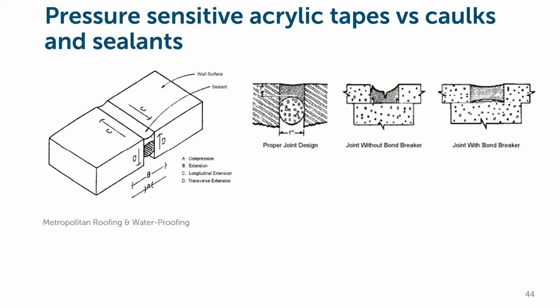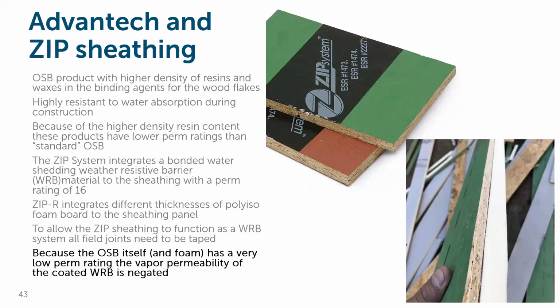But something I see all the time is that people tape their joints and everything, but they're not taping the rough opening sheathing back to the studs at the ROs, and they're not taping the Zip system at the base where it meets the pour. It's great, you can tape your Zip system all you want, but unless you're taping every single key joint, you're only as strong as your weakest link. Yep. Thank you. That's a good point.